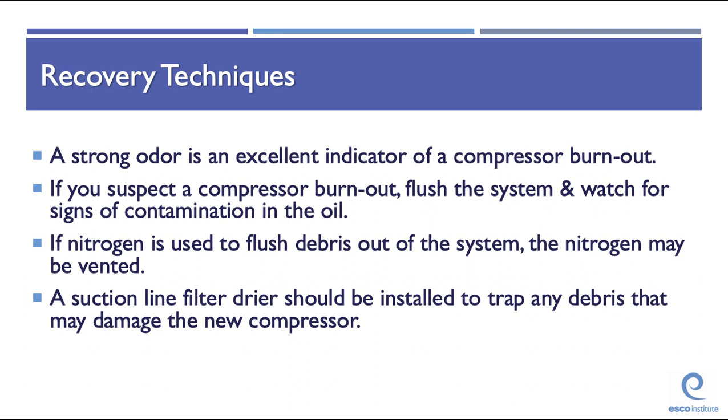If a strong odor is detected during the recovery process, a compressor burnout has likely occurred. When recovering refrigerants from a system that experienced a compressor burnout, watch for signs of contamination in the oil. After recovering refrigerant, if nitrogen is used to flush the debris out of the system, nitrogen may be legally vented. A suction line filter dryer should be installed to trap any debris that may damage the new compressor.